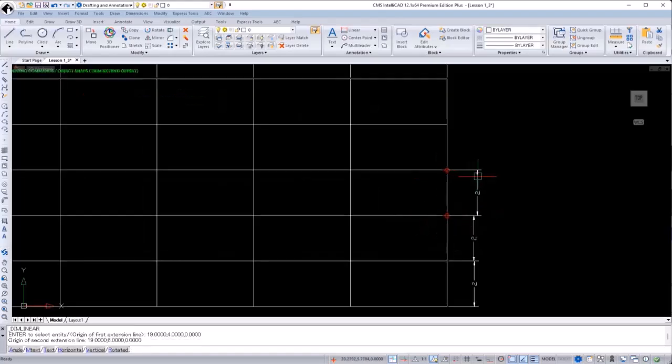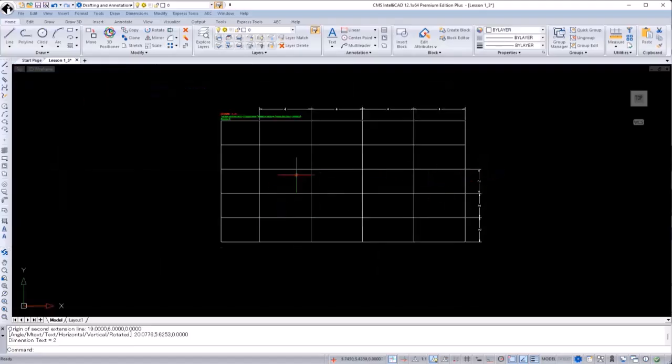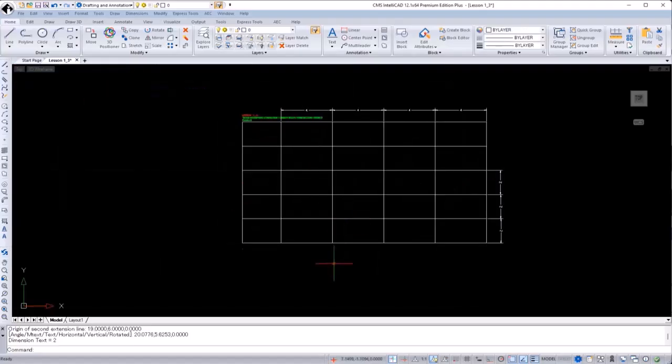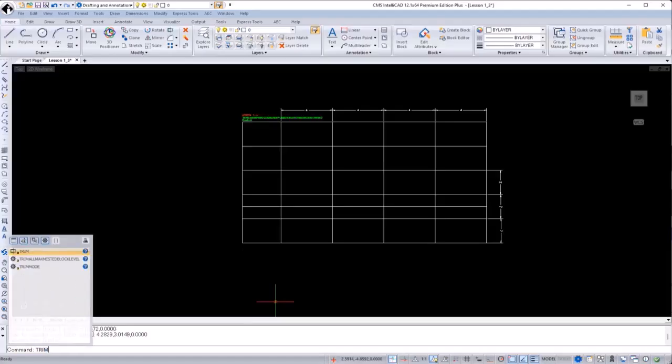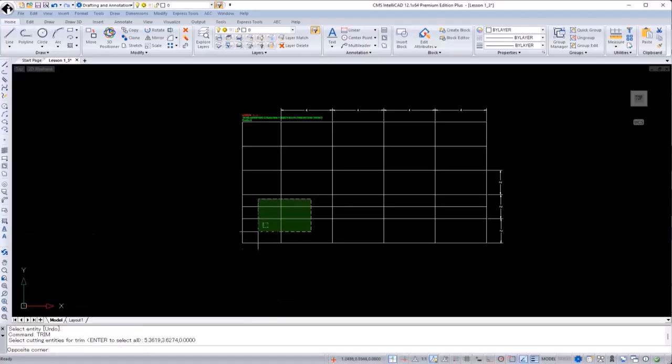Now that our dimensions are labeled, I just want to show you again how easy this is to offset. So we're going to reset the offset tool to 3 units and drag upwards from that bottom line, and it goes up 3 units. Then if we wanted to, we could select a number of these segments and use the trim command in order to start trimming off segments that we don't want.